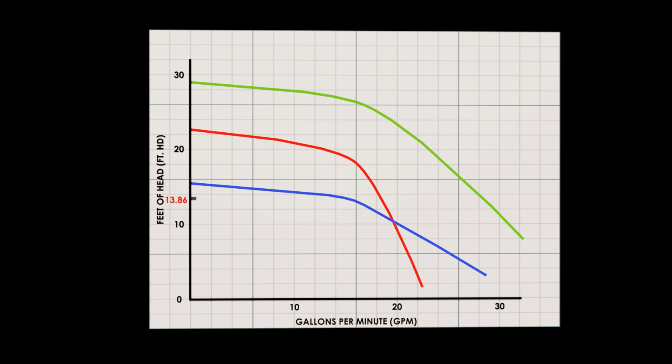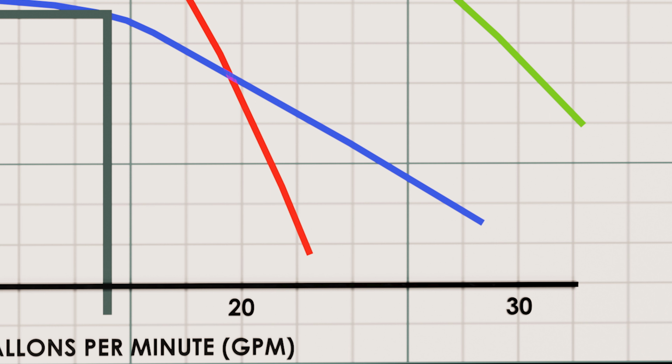All we have to do is draw a line from the headline until it intersects the impeller curve. Then draw a straight line down. Our flow rate is revealed where our line crosses the flow line. And as you can see, as the head pressure applied to the circulator is reduced, the flow is increased until we reach the end of the curve. The end of the curve represents the absolute maximum flow the circulator can achieve, but the maximum flow is generally